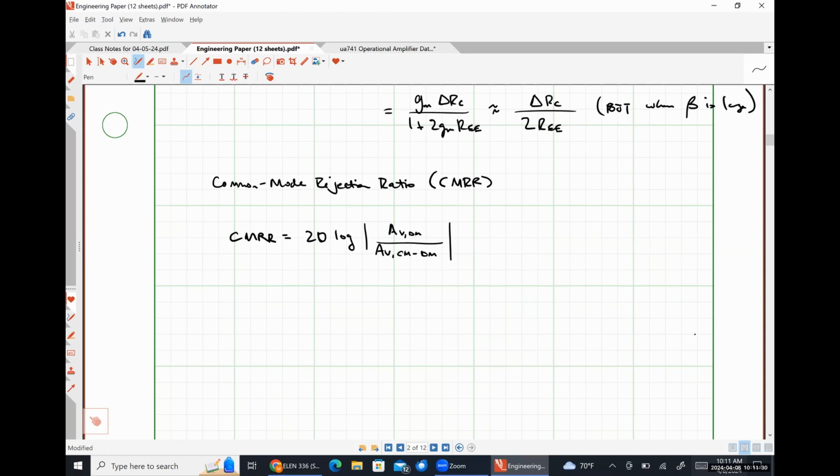So your first design project is going to be to design, I'm going to call it, a simple, not particularly difficult amplifier. I think if I remember correctly, it is a common source amplifier. All of the capacitor sizes and all of that kind of stuff are going to be given to you. You just need to find the resistor values based on the design criterion.